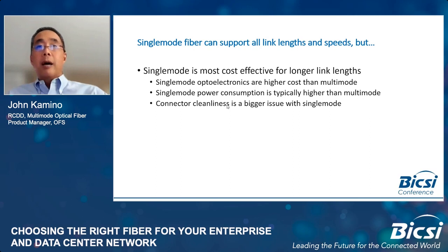But the optoelectronics, the transceivers, are going to be more expensive than they are for multimode. Single mode power consumption is typically higher than it is for multimode. And then last, and maybe the most important from an operational perspective, connector cleanliness is a much bigger issue for a single mode fiber installation.